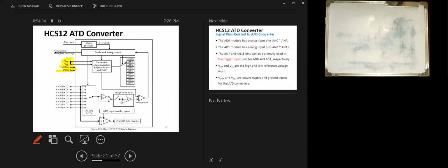So you may have reference voltages from 0 to 3, but the A to D has to be operated by, let's say, 5 volts. Why do we have separate input power supply pins for the A to D? Because it is an analog device and its operation is very sensitive to changes in the supply voltage. If this is the microcontroller and this is your A to D,